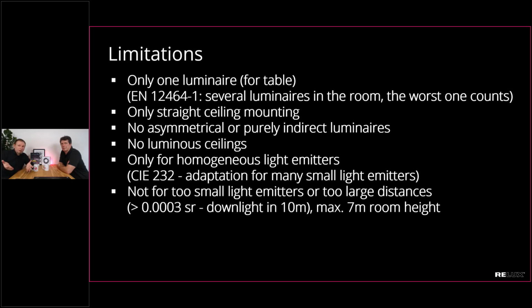And yeah, if you have a large indoor area, a hall, whatever, which is more than 7 meters. The 7 meters is not in the CIE 117; you have just this solid angle, but 7 meters is from practice. A lot of papers reference the 7 meters. Beyond 7 meters, you should think twice about using UGR. But this is limited by the solid angle, which you can calculate for each luminaire, for each observer. And if you have a value less than this, then it's just too far away.